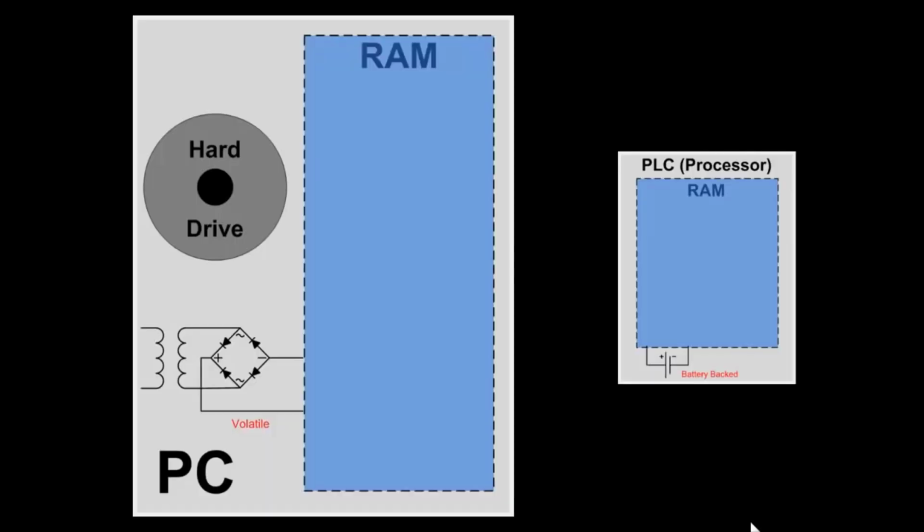Here's what we'll call your computer scape. You have two computers. You have a desktop or laptop, we'll call it the PC, and you have a PLC. Now this is without using Emulate. This is the standard conventional way to learn to program a PLC. You need a computer to run RSLogix 500 and RSLinx on, and then you need a PLC to download to that has some switches on it that you can flip and exercise your program.